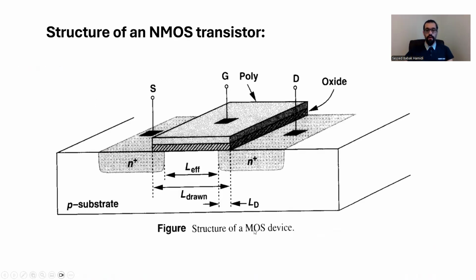This is the structure of a MOSFET device. By MOSFET, MOS, we mean metal oxide semiconductor. When you say semiconductor, it means the substrate that your electronic or electrical circuits, other terminals, and other components are built on. That substrate should be a semiconductor. A very standard substrate that all our chips, ICs are built on would be silicon. So this silicon substrate would be a P substrate.